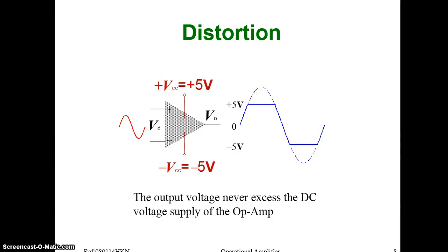For that reason only I told you to give voltage in the millivolt range. You all must have given 10 millivolt peak to peak. Some must have given 20 millivolt. So this is the reason. We do know the gain of the amplifier, so sometimes the output can exceed the supply voltage, and surely we will get a distorted output.